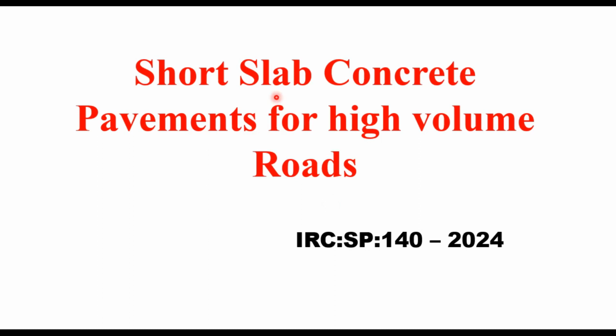Hello friends, today we will be discussing short slab concrete pavements for high volume roads, meaning national highways and expressways. The guide for this session today is IRC SP 140 2024. These are concrete pavements with short joint groove spacing of 1 to 2 meters.